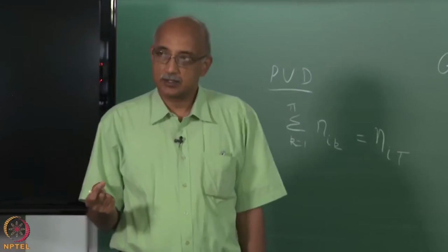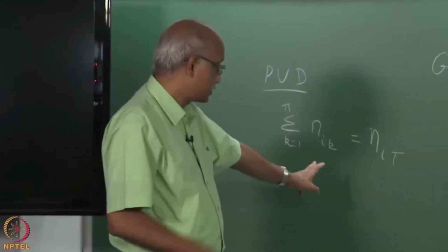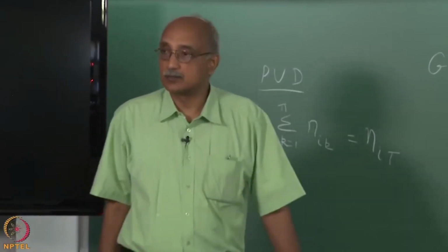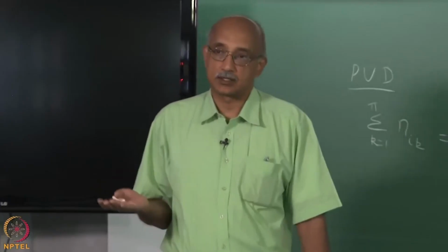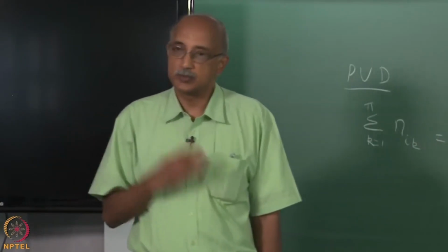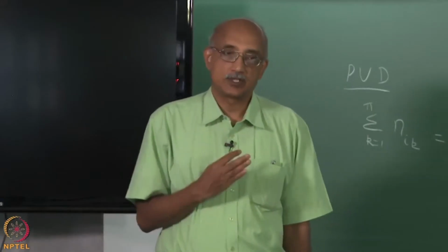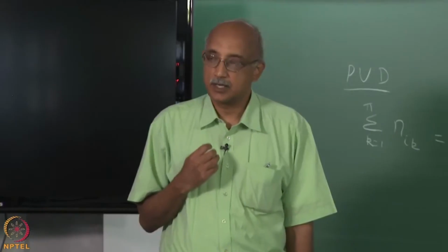In a CVD reactor, how would this constraint change? It is not enough. In fact, this equality would not apply in a CVD reactor, because the species will not stay intact, right. They will be transformed into other species. So, how do you handle that? How would you impose a mass conservation condition in a CVD reactor? Any ideas?